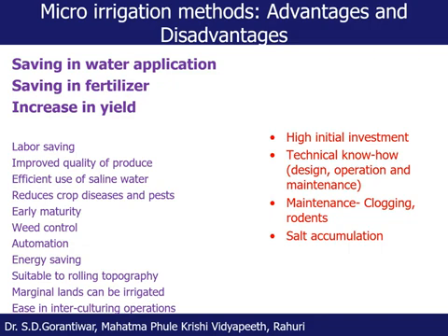But in case of surface irrigation method, the practice is different. Okay, so we cannot apply fertilizer with every drop of water, and whenever we apply fertilizer, and after application of the fertilizer we apply water, and as water is moved beyond the root zone in unwanted area as well, fertilizer will also reach to the unwanted area.